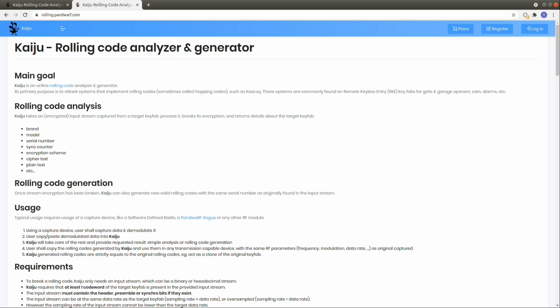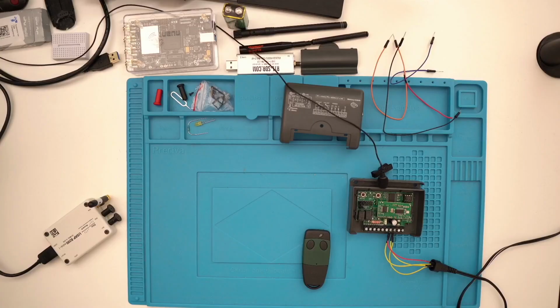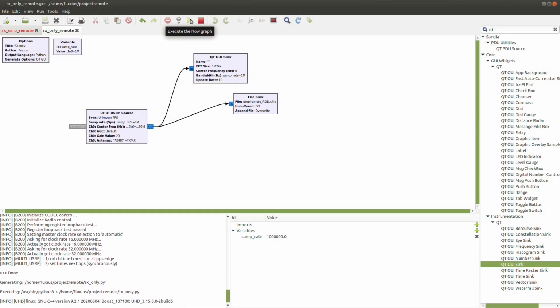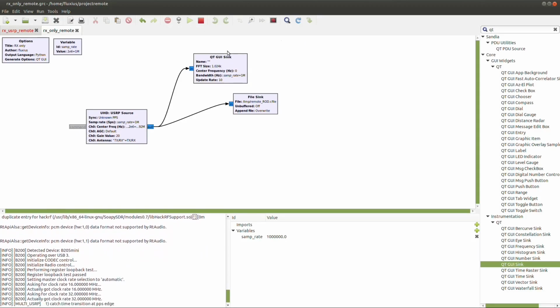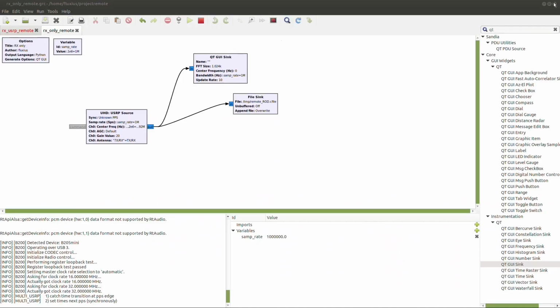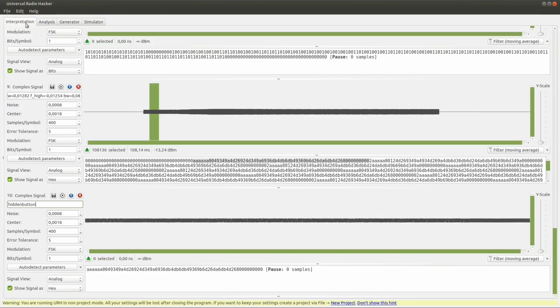What I will do is make another capture. I will just capture another key press because I also need a fresh synchronization one, and I'm not sure about the one that I have provided. So I will make a capture in here, push a button, okay, and then I will analyze it directly with URH. Like that I can copy directly all the bytes.